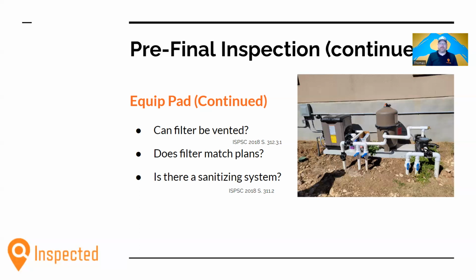And that pretty much negates the function of a sanitizing filtration pump. So make sure there's a means by which to sanitize the water. As long as it's properly sized, it can be chlorine, bromine, salt that creates chlorine, UV ozone, AOP, copper or silver ions, whatever works for you and your clients, as long as, again, properly sized.